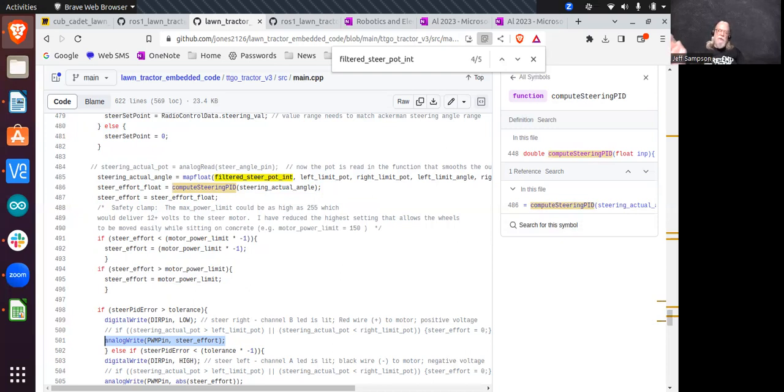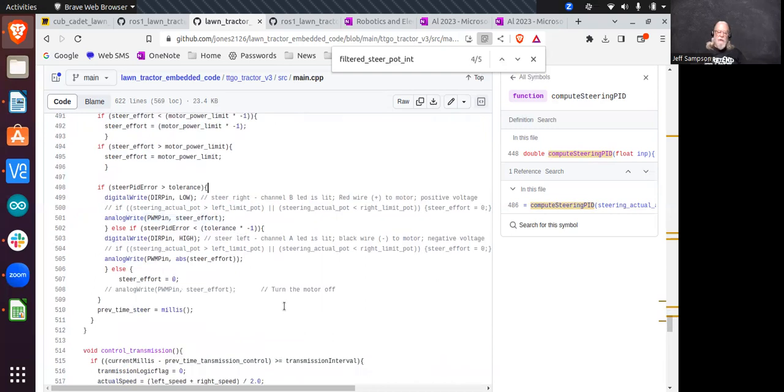So if the thing is going towards the hard stop like this and passes this point, it just kills power to the motor, so it can't go any farther. But if you move it the other way, it can still back out of that. And at one point you had implemented that. I don't remember where we talked about that, but I think we discussed this in one of the meetings, and then you actually put some code in to do that.